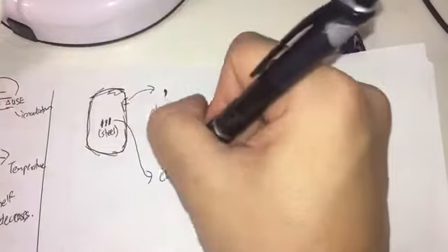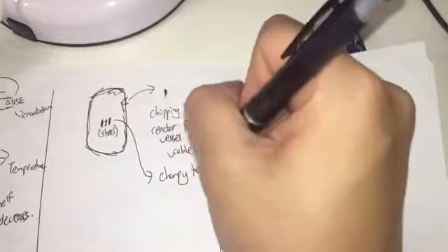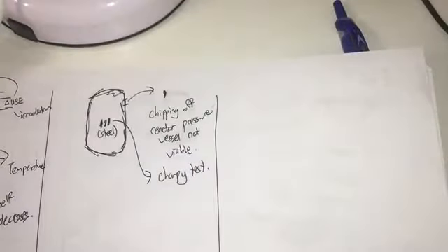Every year or so, probably during a refueling, they take one of these lumps to do a Charpy test. You can imagine this piece of steel will be pretty radioactive, but that's the idea, so that you don't have to damage your vessel.